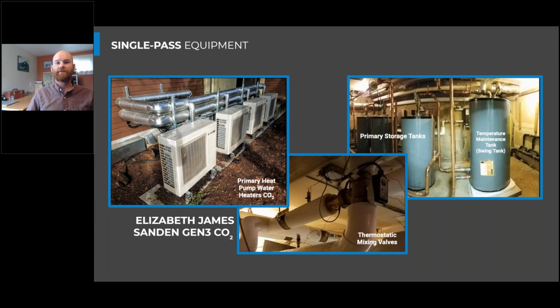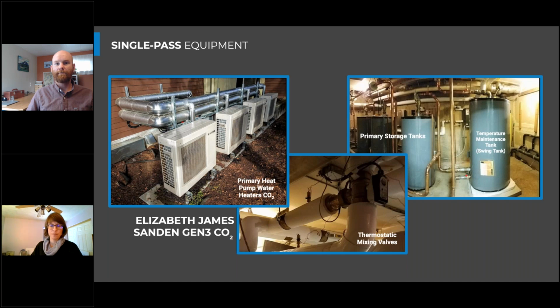Then in the early hours of the morning, it's going to have swung down in temperature closer to 125 degrees in the storage tank. So now we went from 150 to 125 on the hot side of this mixing valve, or excuse me, 140 to 125. And so it's really important that we have good control over those mixed outlet water temperatures, so we're not scalding these senior occupants.